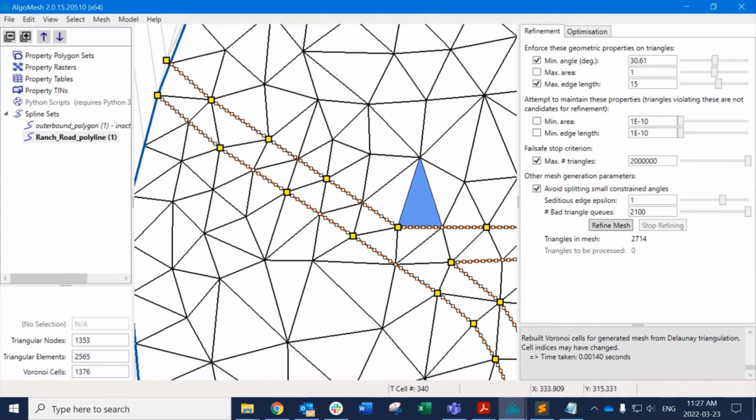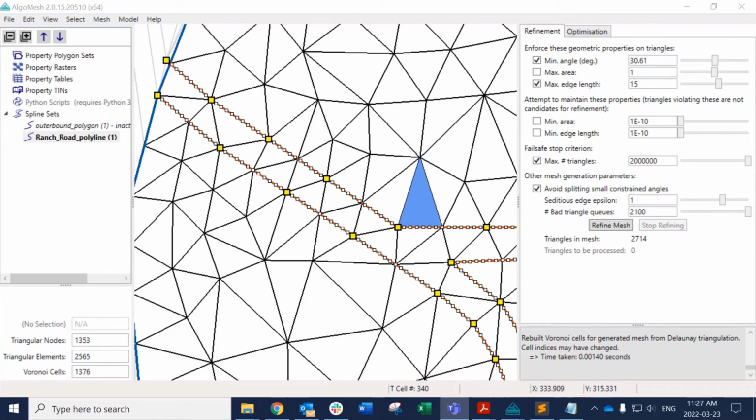Yeah, I don't think you should ignore any of them, but definitely the most important is going to be your aspect ratio, and just your total node count and the range and size of elements. So that's something you could get from the actual eco file or echo file in HGS would give you all of those straight off. But it's really the aspect ratio that is probably the most informative when looking at it within AlgoMesh itself. Looking at values really above 0.5 is kind of what you want, but as close to 1 as possible being ideal.